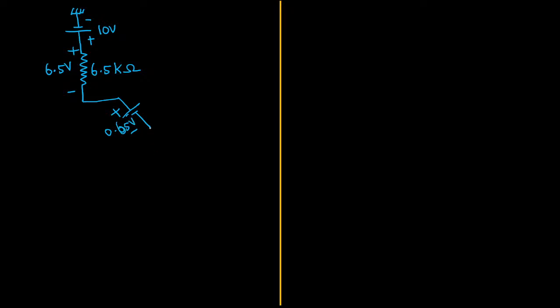After that, again, we are crossing the second transistor, but for the second transistor I am going to cross the collector to emitter terminal. Then at the bottom we have a 1 kilo ohm resistor. Just observe the circuit. The voltage drop across this 1 kilo ohm resistor is given as 1 volt. Now, can you apply KVL? The only unknown is this VCE for the second transistor.